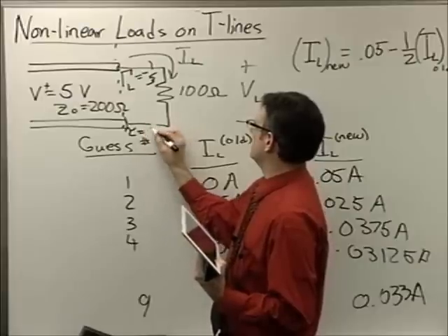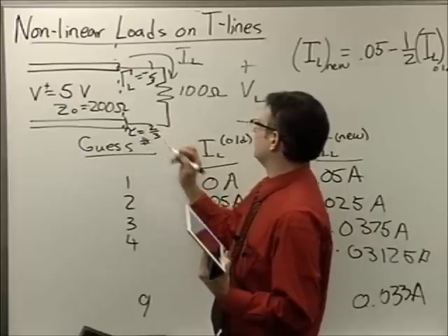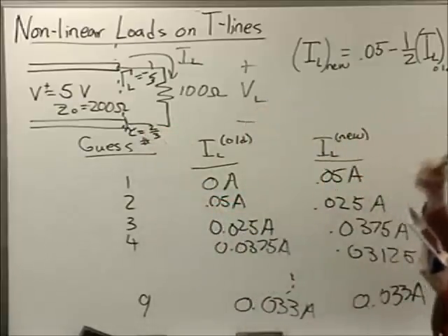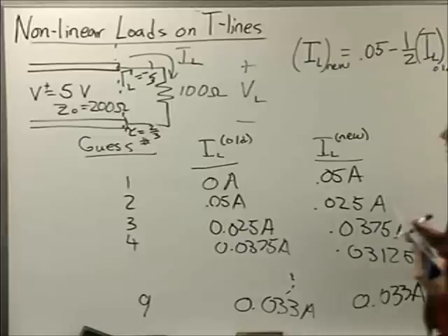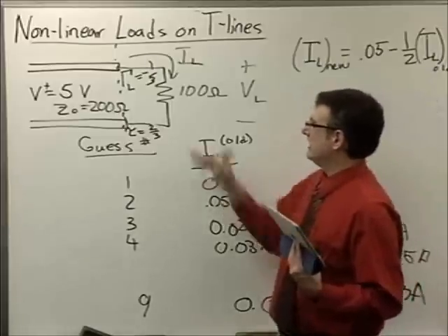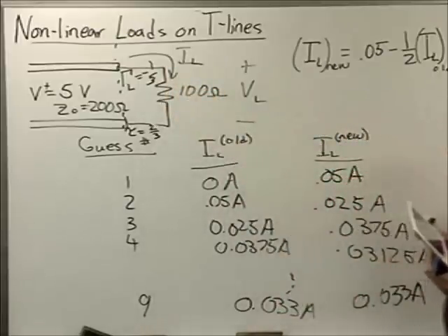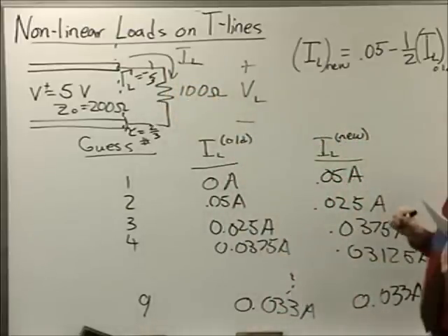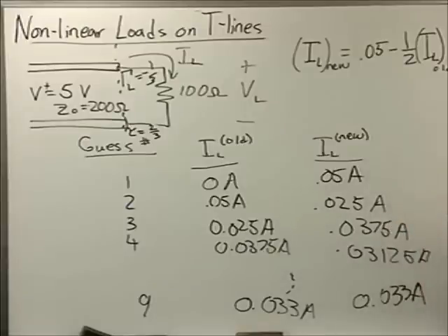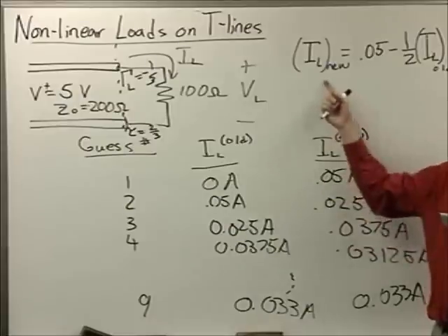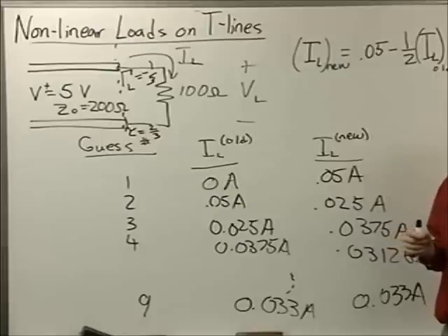Is that right? So I should basically get 10/3 of voltage across here. And that, when I divide by 100 ohms, should give me 0.033 amps. So you can see the long way wound up equaling the short way in terms of our solution.